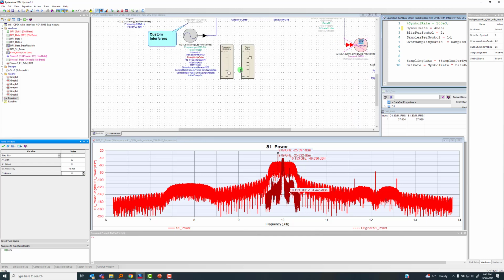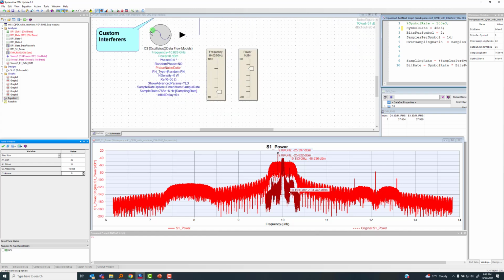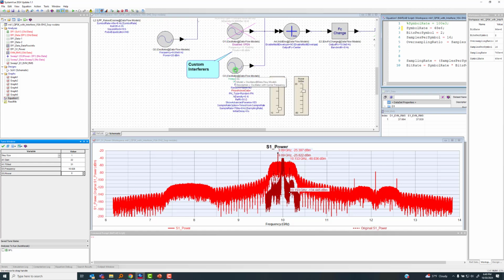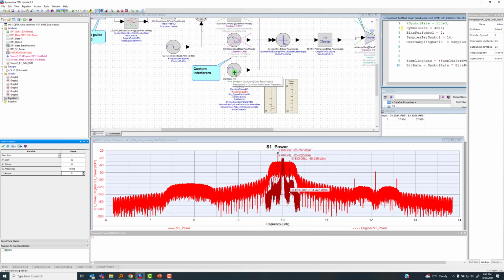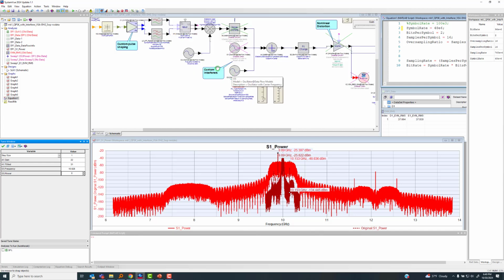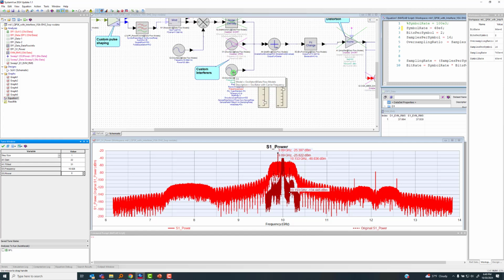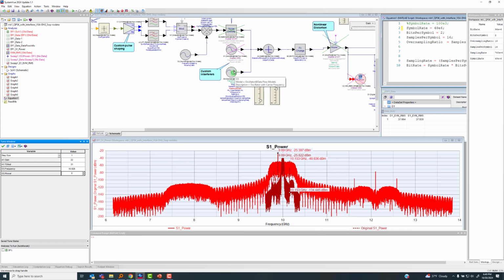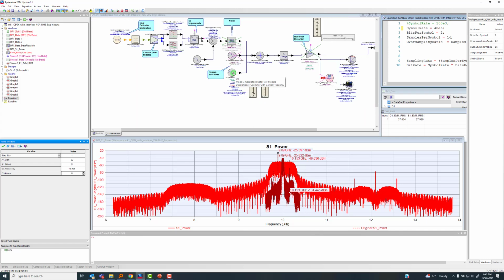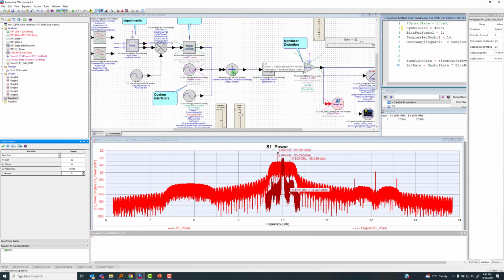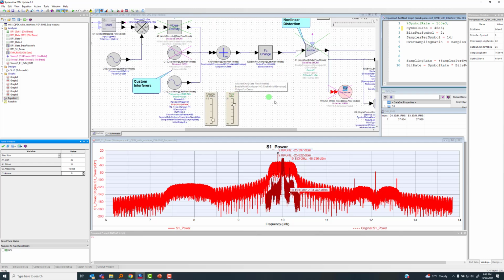This is also reflected on these tune bars that are governing the interferer signal here. Now this is a CW signal, but there are a lot of other great examples you can play with. These could be totally different modulated signals or susceptibility signals or coexistence signals that you need to test. SystemVue can add them together pretty quickly and easily.